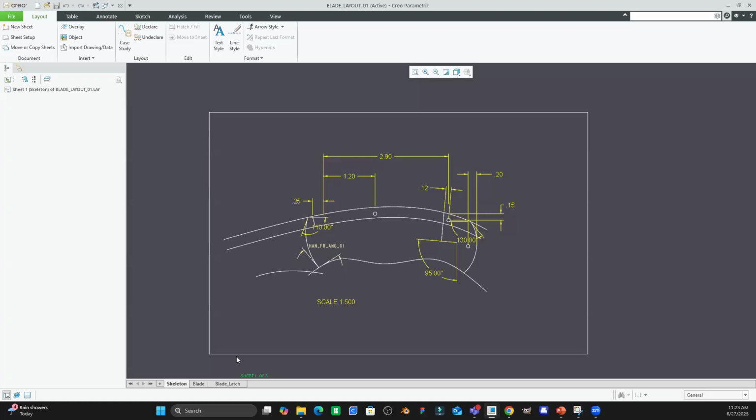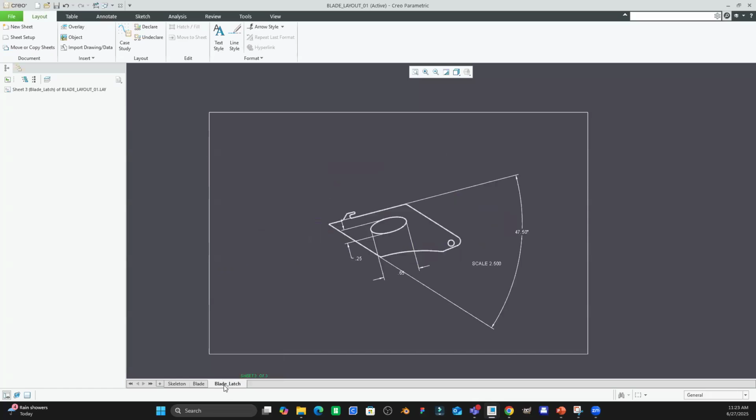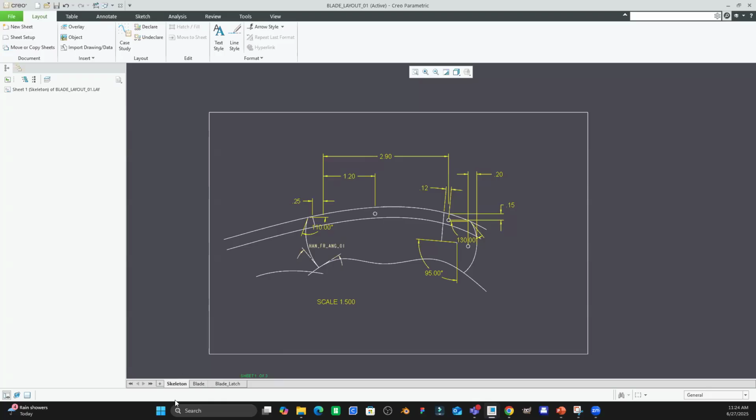So you can say, hey, these are all the sketches, these are all the parts and the parameters that were created from them, so that when somebody has to figure out how an assembly was created, they can just take a look at the notebook and the skeleton part in the assembly and say, okay, this all makes sense now. I can see where their mind was at when they structured this.